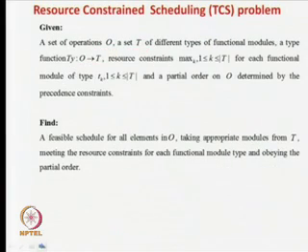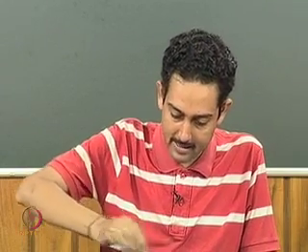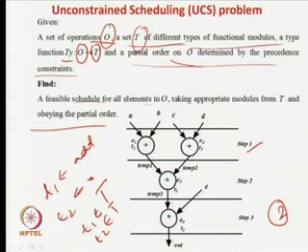Okay. Now, let us see. Let us define. In the last example, you can say that it was an example of time constraint scheduling when your time requirement or deadline was 3. Okay. So, in this case one more thing you have to observe. In this example, this is a scheduling problem with time constraint 3, which is satisfied. If I tell you that I want a similar schedule, but my time constraint is 2, you will find that I will land in an inconsistency, because you cannot do everything in 2 time steps. You cannot compute this in parallel with this one, because the results of O1 and O2 are required to get the value of O3. So, you cannot put this one here, it is not possible.